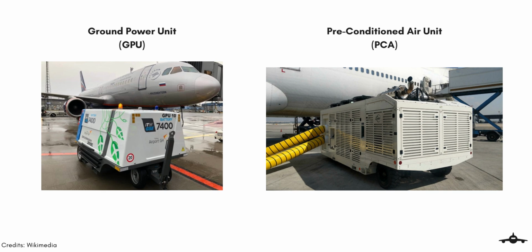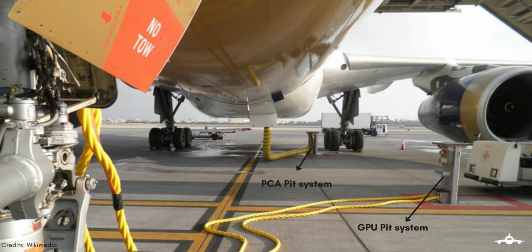When an aircraft lands and reaches its bay, it requires a ground power unit, a PCA unit, and in some cases, refueling. For example, a ground power unit is provided by any of the types we have studied in the previous lecture. Nonetheless, either the GPU or PCA unit will need to extend its cable or hose to the aircraft. These wires and hoses may create clutter on the bay. Apart from that, it takes time to extend the cable and hose on the ground in a safe manner and to make the connection with the aircraft.